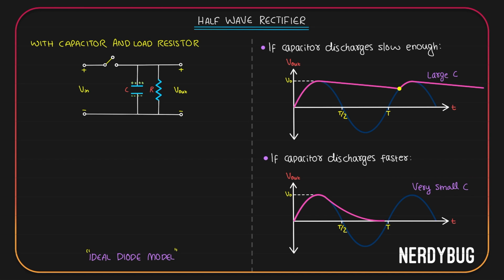In the second case also the same thing happens. The only difference is discharging is exponential. So the drop in voltage across the capacitor is also exponential. The voltage drops exponentially like this. It becomes 0. But at this point, voltage across the capacitor is equal to the input voltage. So on both sides of the diode, we have equal potential, that is 0. After that, voltage across the capacitor tries to be 0. Input increases from 0 to its maximum value.